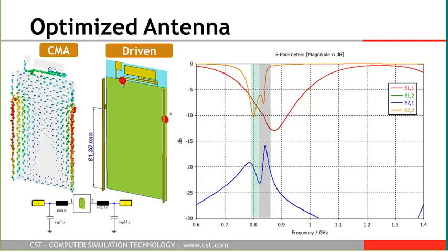So we have port 1, which is a red dot on top, exciting the primary antenna, and port 2, the red dot on the right arm. Finally, we need a matching circuit displayed below, and to optimize the values of this matching circuit. And you can see the final optimized design.